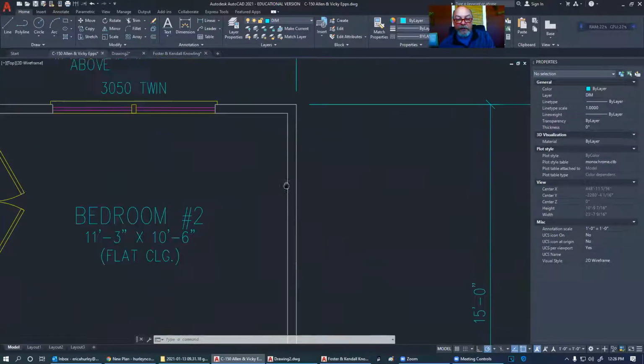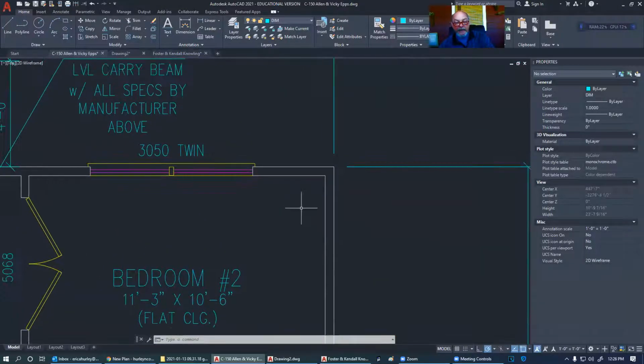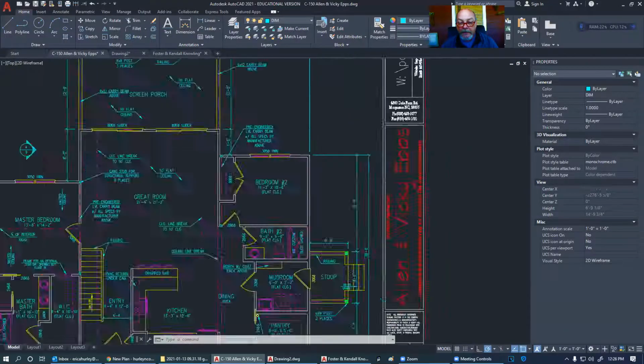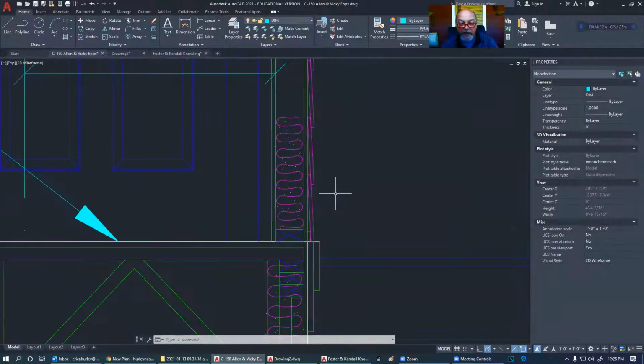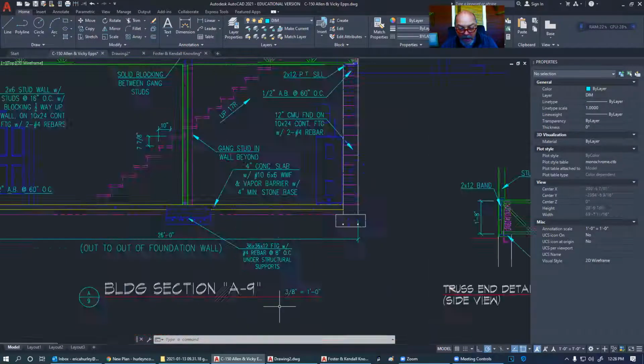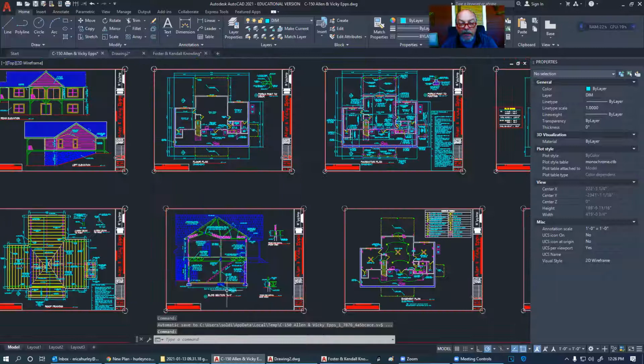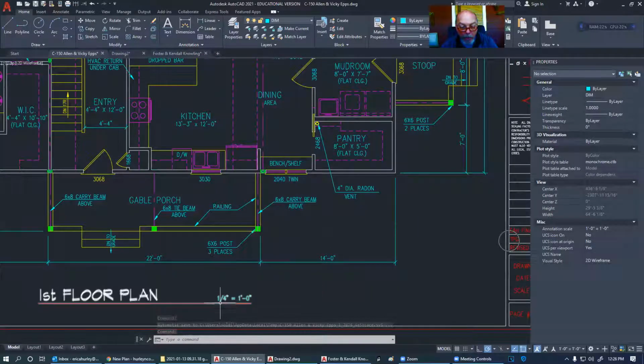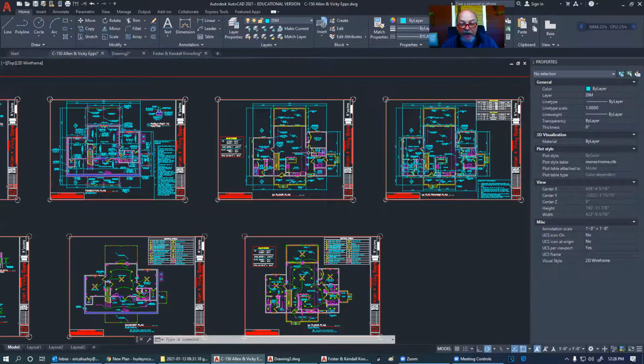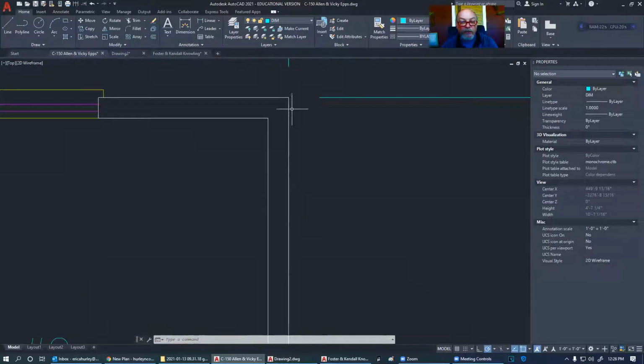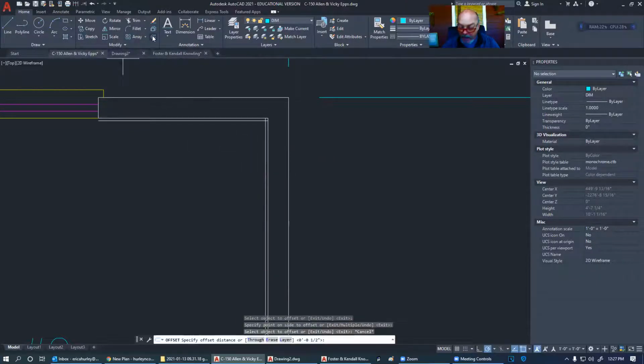Let's look in here. Notice that here is an outside wall, and I'm not showing the stuff that we see on the section. The sections are at 3/8 inch per 1 inch, where these floor plans are 1/4 inch. So these are smaller, and look at how this is going to get real dirty really quick. I'm going to add the 1/2 inch drywall to the inside, and I'm going to add the 7/16 sheathing on the outside. And then I'm going to add the siding.